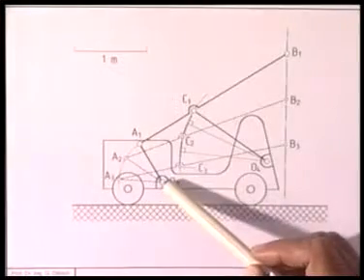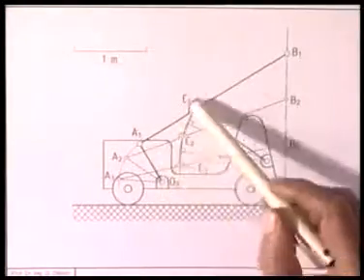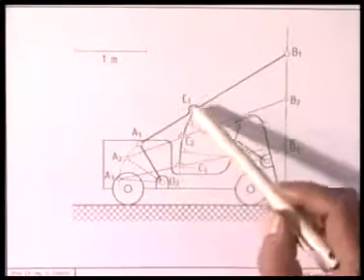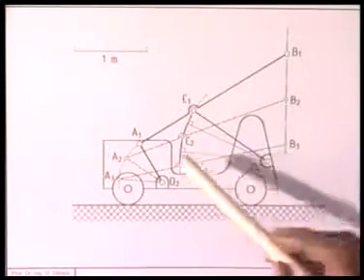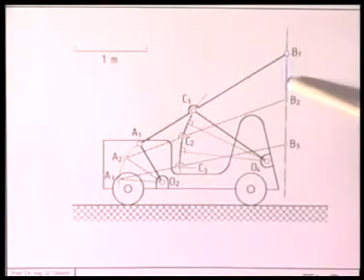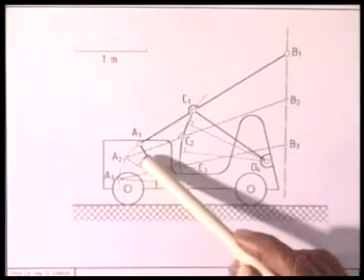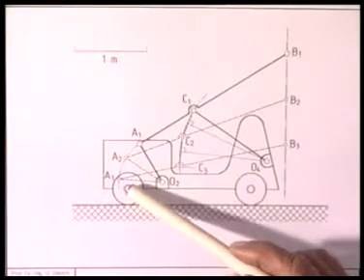So at this stage, that is at the end of the second stage, I have got to a 4-bar linkage, namely O2 A C O4, such that when this 4-bar link moves, this coupler point B1 has the desired movement and is also coordinated with the input movement.